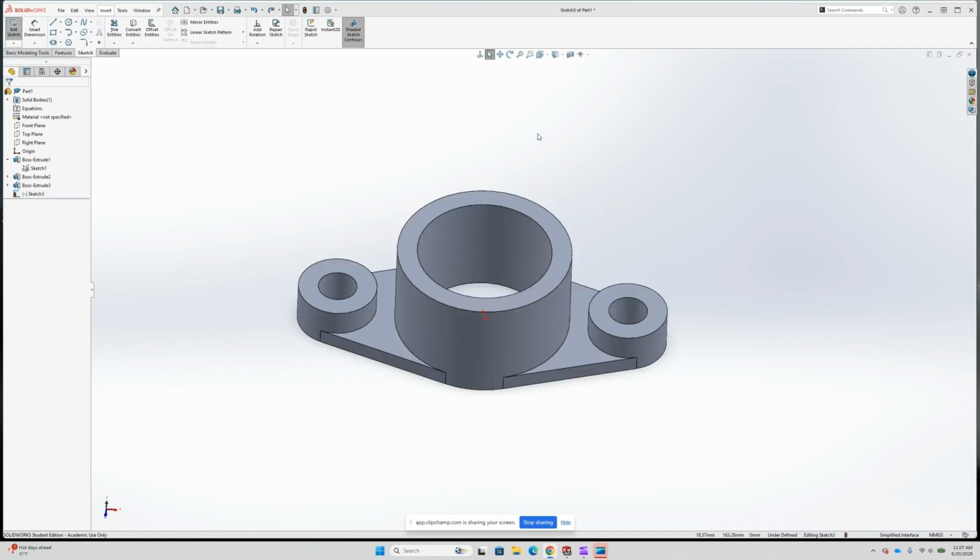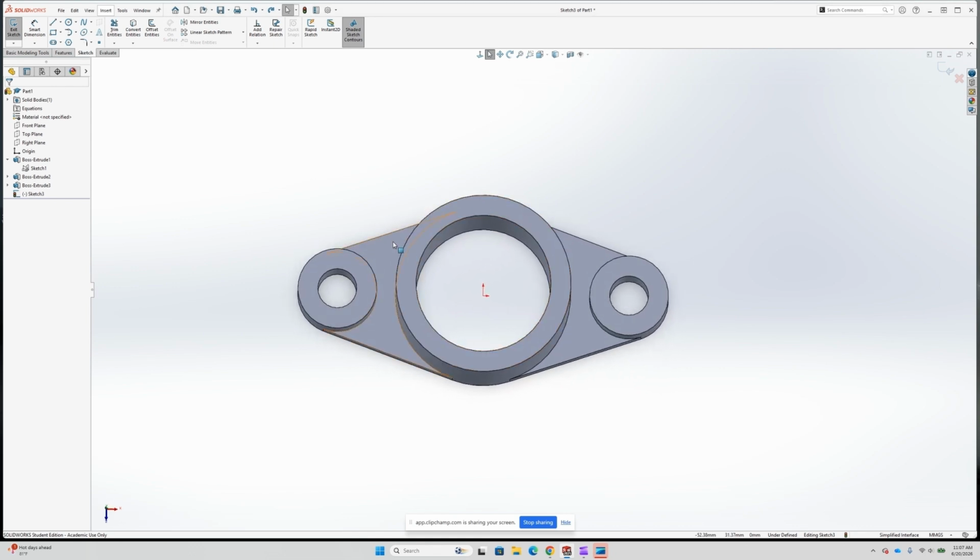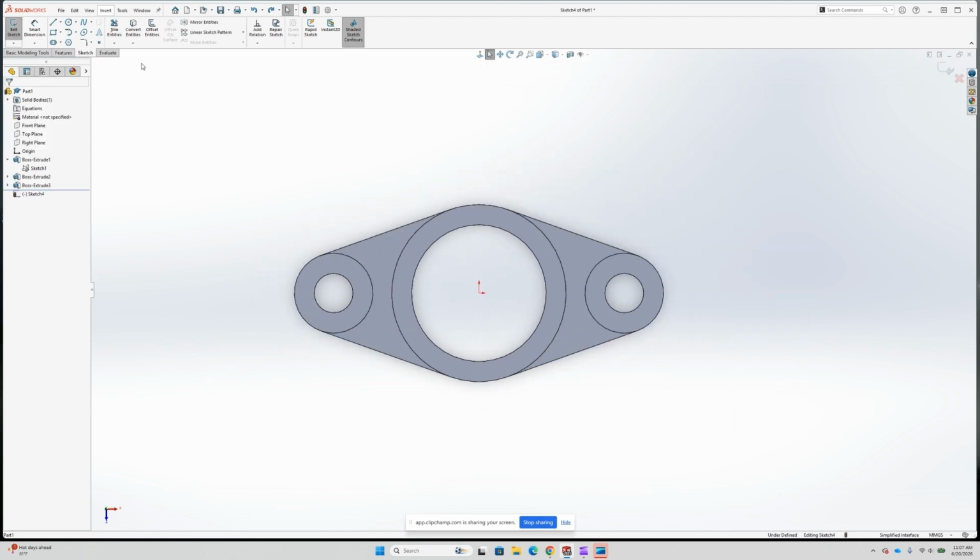So now we can move on to the final step, which will be those kind of crooked hourglass cuts in between the circles. So we'll click sketch, click on the face, and then we will click offset entities because it is 3 thickness throughout. We'll click this face, click offset of 3. If it's not showing at first, just click reverse the direction, and then click OK.